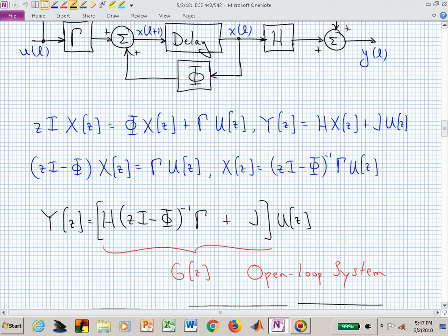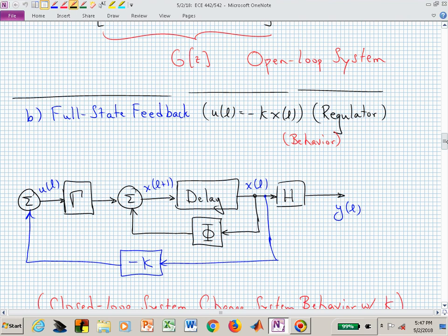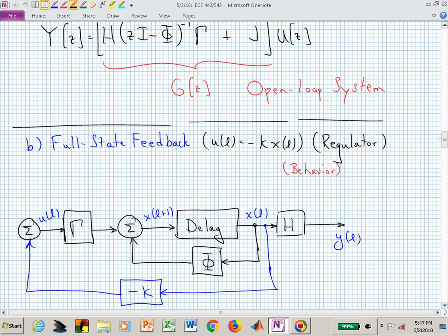That's the first block diagram. That's just really one way to visually see those difference equations that model the system. If we weren't happy with the modes in phi, we could change those by going in and measuring the state vector x, scaling each of those with some constant, and creating the input u that drives the system by saying, oh, that's minus K times the state vector x.